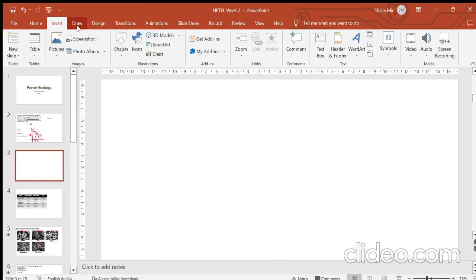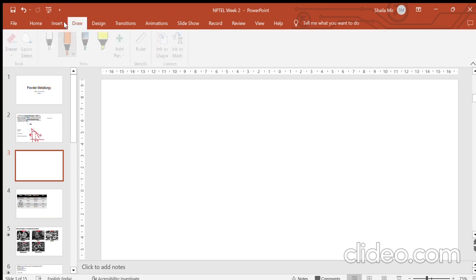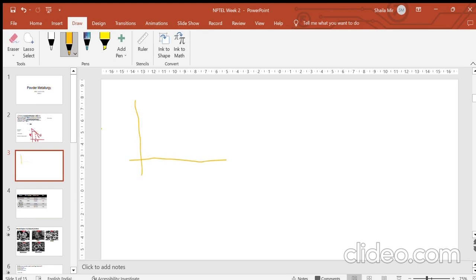If we have a characteristic graph, this is the energy, the delta G value, and this is the temperature. When you see this delta G value, it can be positive, it can be negative, right? So there is a balance between the two energies as nucleation proceeds.